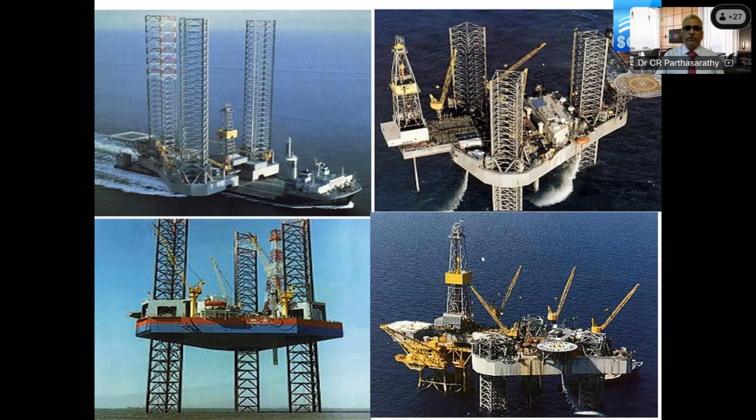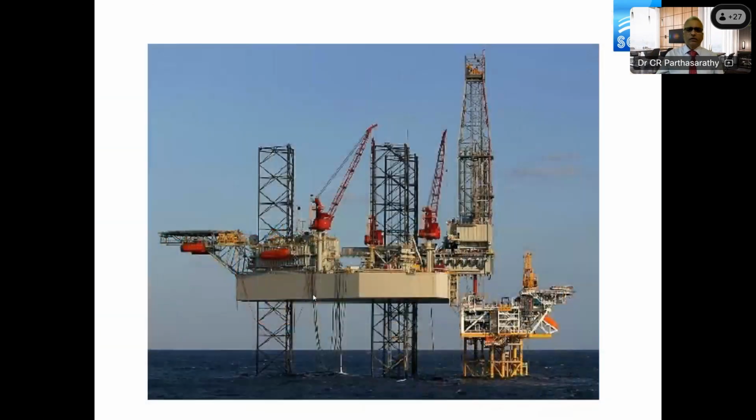Okay, so this is for an open location where you want to do the exploratory wells. Now once the fixed platforms are installed, you can see the jacket structure. The jack-up rig will come adjacent to the jacket structure for the second time to drill the well through the conductor pipes. Here is the jacket structure, which is already installed on piles. Then the jack-up rig will be positioned adjacent to the platform. The cantilever goes on top of the jacket through these conductor guides to drill the wells.